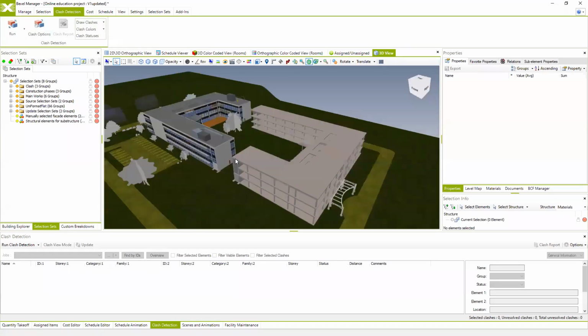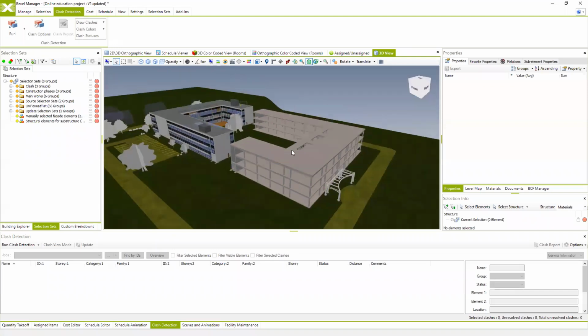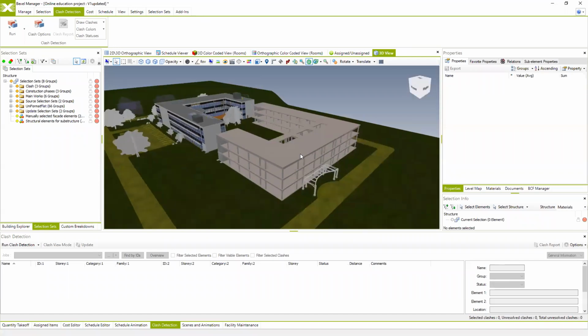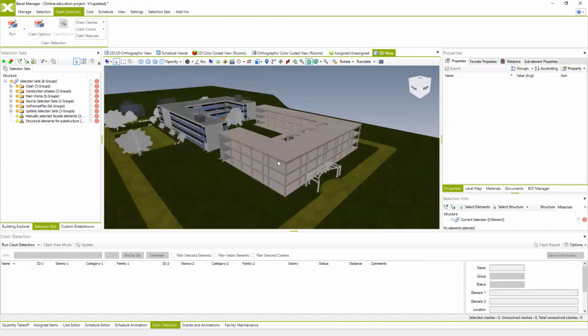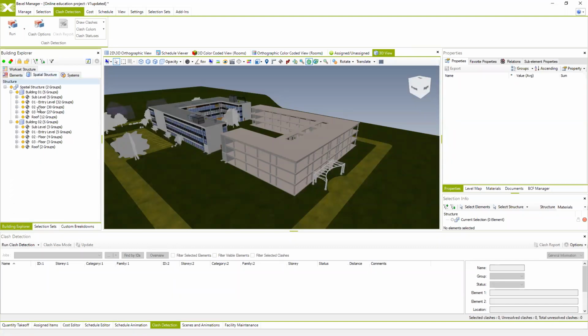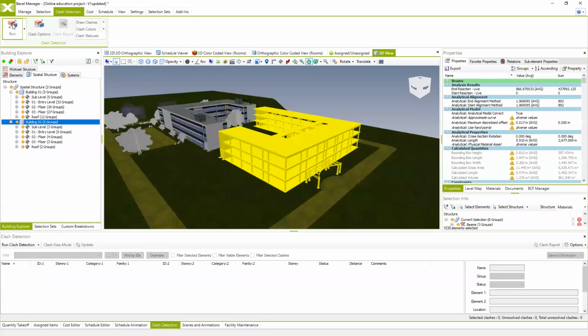If you just want to check if your BIM model, which we updated with this new structural building, has some duplicate elements, we can easily select these elements by selecting the structural elements from the BIM model using already created selection sets, or using the spatial structure, whatever we choose, and then use the option to check duplicate elements.